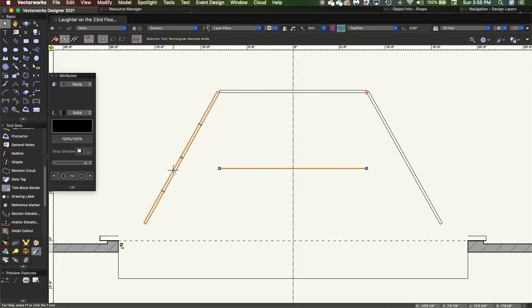Now it clearly does not intersect either one of the other walls because they're out at a 30-degree angle. But we're going to go back to our Connect Combine tool that we used clear back in the beginning of part 1 of the tutorial. I'm going to click on that. I'm going to grab this line and bring it over to this wall and click, and this wall and click. And now I've extended that line all the way across.